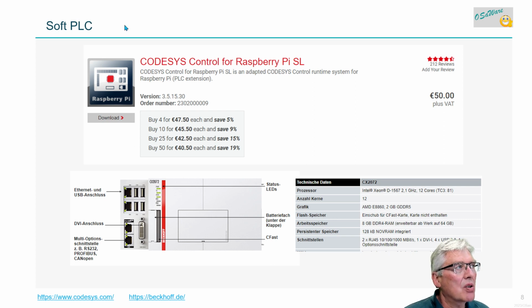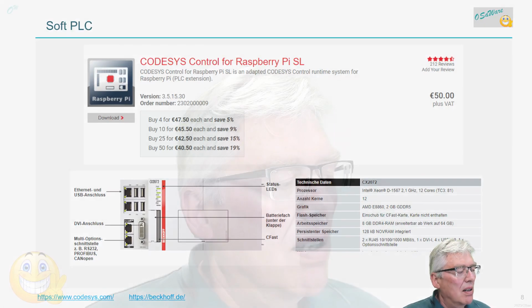Basically a soft PLC, running a special operating system and being programmed with Codesys, but they have embedded Codesys into Visual Studio. So it's a really good editor, really fast and good. And this system, I think it can run on here's a 12 core. I think it can execute on up to 32 cores. So it's a really powerful system, high quality hardware, and really fast. So that was the end of that. So this was an introduction to PLC evolution.